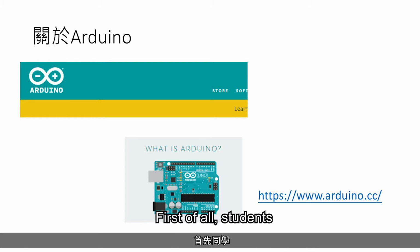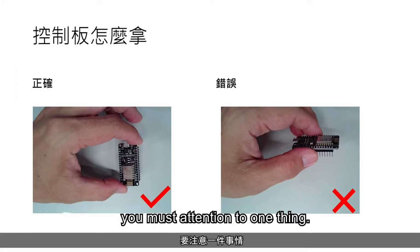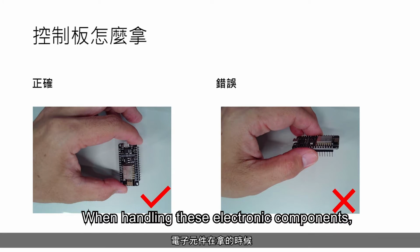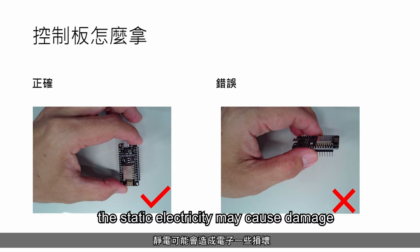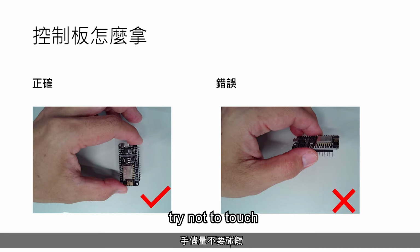First of all, students can take out the control board in their hands. Let's explain. When you take it out, you must pay attention to one thing when handling these electronic components. Why? Because everyone has some static electricity. The static electricity may cause damage, so when you are handling it, try not to touch the metal pins.